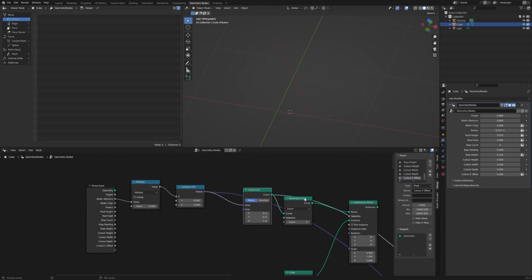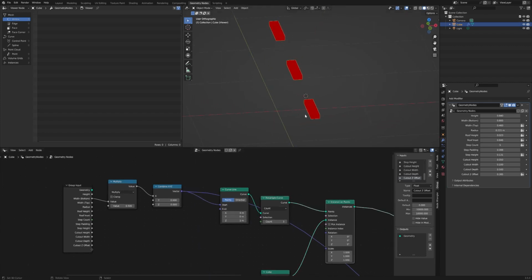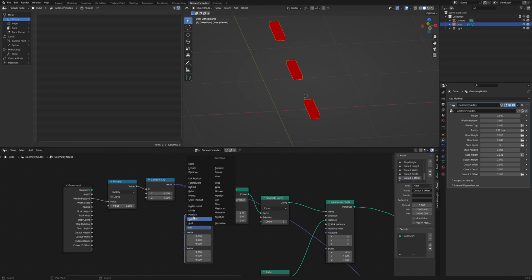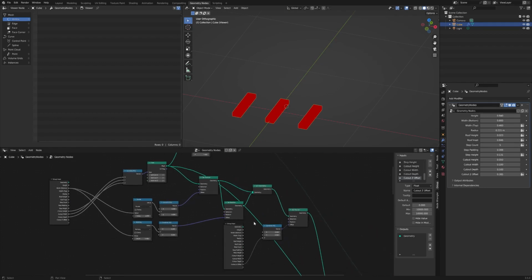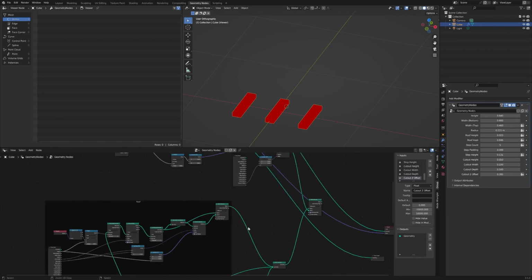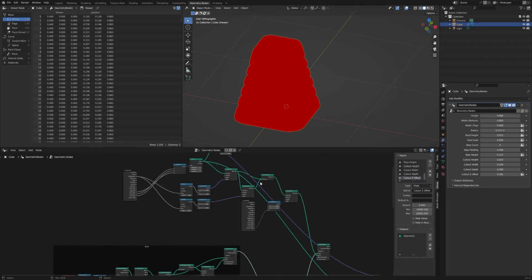Then now when we have our curve line, at the moment it's going from here. We also want to have that at the end as well, but we're going to have that mirrored. So rather than just injecting that into the end, we can then do a vector math multiply. The vector coming out is then going to be mirrored in the x-axis, so we want to multiply the x value by -1. There we go. So now that should line up nicely to our actual base geometry. So if we take the geometry from here, there we go. So that's now centered quite well.